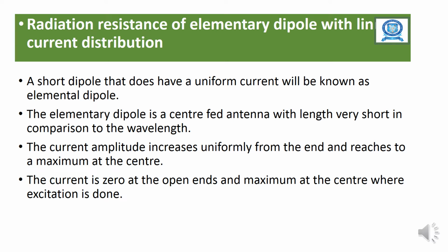So the current amplitude will be continuously increasing from the end, and it will reach the maximum at the center point. Similarly, the current is 0 at the open end, and it is maximum at the center where the excitation is done.